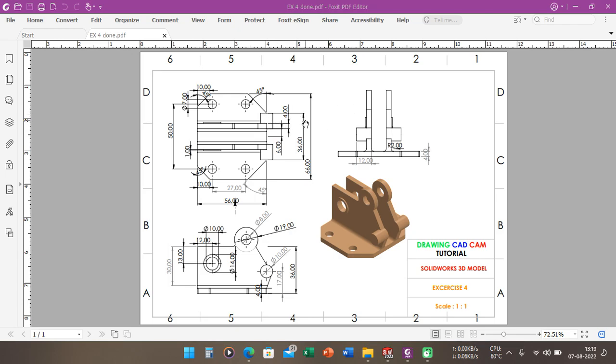On this sketch I will just make the plate with just one plate here, and I will choose the features command to copy this plate later. So we just make one plate here on the center point, and the distance from the center point to the inside of this plate is 6 mm. Okay, so we can draw this sketch.